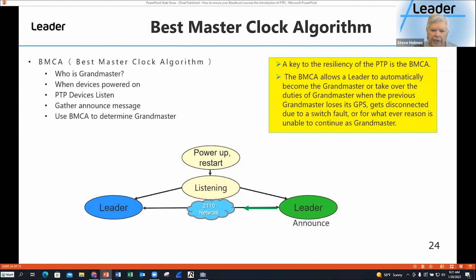Then this voting will come up that we call a BMCA, Best Master Clock Algorithm, and it will then decide, because both units will run that BMCA, and via that BMCA, one of the units will say, hey, this piece of me is a better option than your piece.